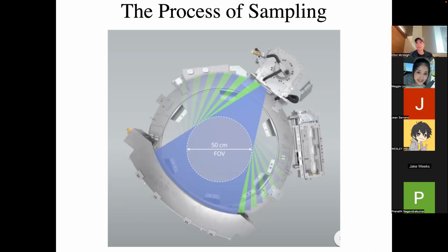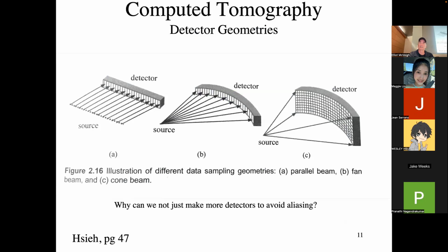One manufacturer, I'll show you some examples when we get there, basically took a plunge and said, we're going to make twice as many detectors on our sampling detector. So they had something that was 1 millimeter by a millimeter, and they said, you know what? We're just going to go all the way to 0.5 millimeter by 0.5 millimeter. So they essentially doubled it in this direction, doubled it in that direction. That's a lot, right? It's 4x the number of signal lines coming out, the number of amplifiers, all of the technology. So the cost goes way up too. So it has to be worth it.